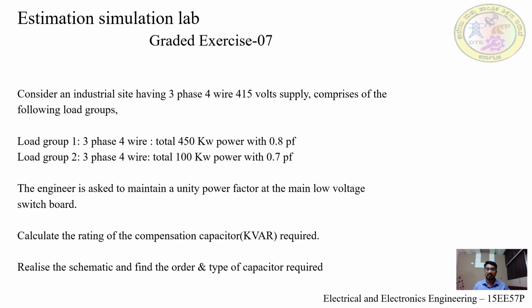The engineer is asked to maintain a unity power factor at the main low voltage switchboard. Calculate the rating of the compensation capacitor required. Realize the schematic and find the order and type of the capacitor required.